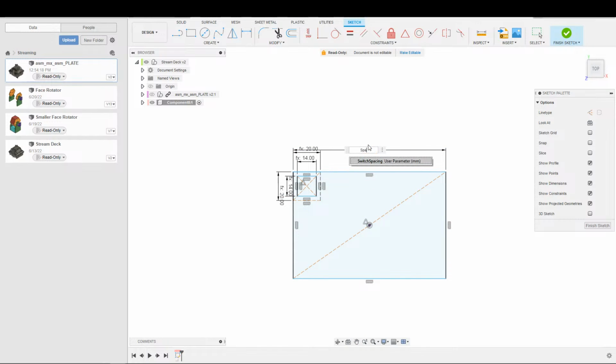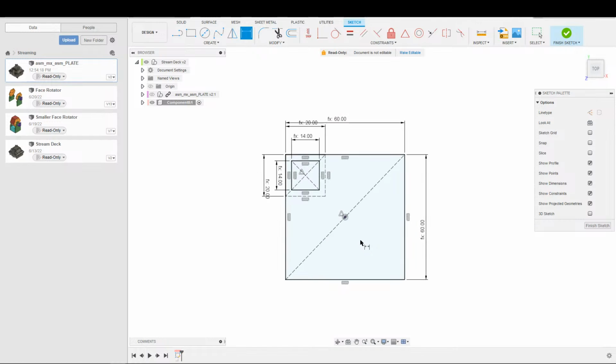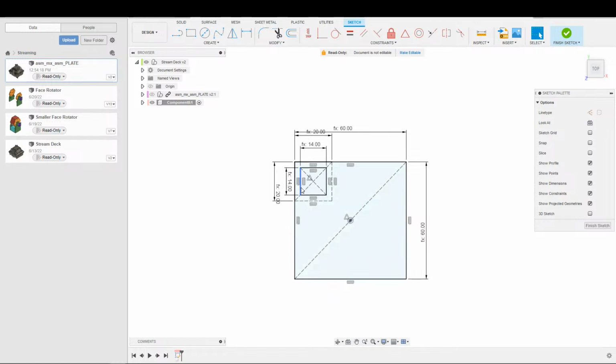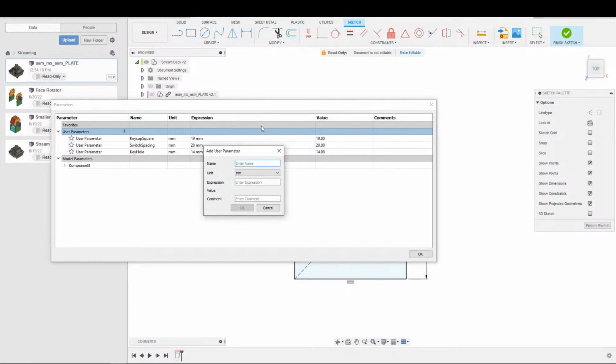So spacing times 3 because we have 3 buttons, and spacing times 3. I could be doing equals here. The reason I'm doing 2 separate formulas is in case we ever want to change it. This key size will never change, but in theory we could change the vertical spacing and the horizontal spacing individually, and we could also change the number of rows and the number of columns here, which actually, just for one of those things, parametric design, I'll go ahead and do that.